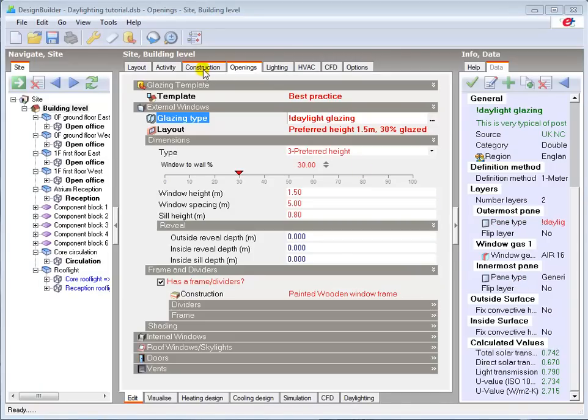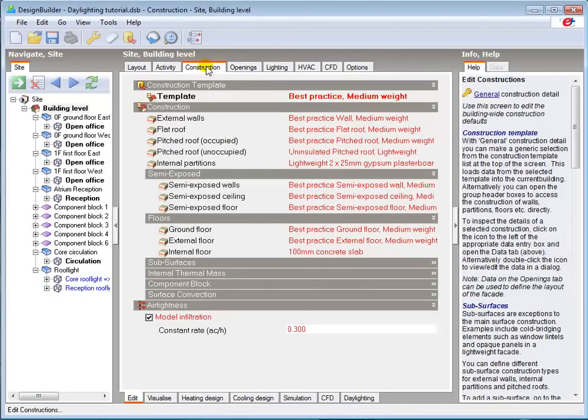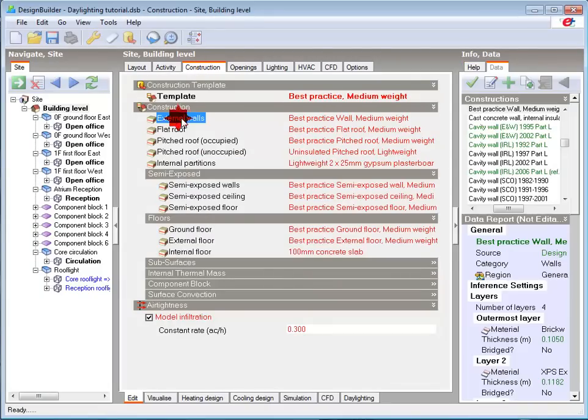The dataset used by Radiance for daylighting simulations also includes construction and site materials data that may not have been previously considered for thermal modelling. You need to use appropriate material surface reflectance values for internal surfaces, i.e. walls, floors and ceilings. Note that the reflectance is simply 1 minus absorptance, and is therefore a value between 0 and 1. This data can be found by navigating to the properties of the zone internal surfaces in the Construction tab, such as the inner layer of the external wall construction here.